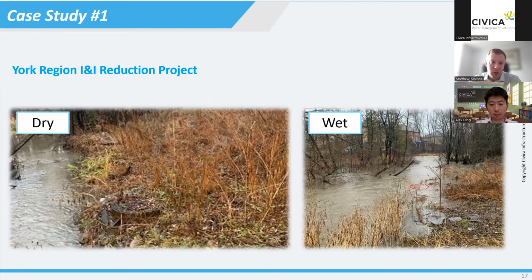The picture on the right, we went back during a larger storm event, still less than a 2-year storm, and the creek had overflown the banks in a sense, or just had swelled because of all the rain. And now where that little red dash circle is, that's the location of that maintenance hole, and that's underwater. So depending on the location, there are a lot of municipalities that are putting in fully bolted down covers and frames, and maybe it would still be good under this situation.